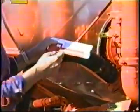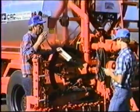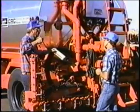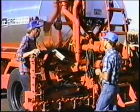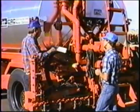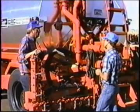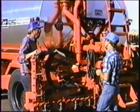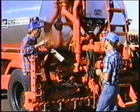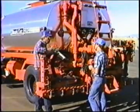Okay, so that means on this truck, all we have to do is hold the engine up to 1200 engine RPM. While we're doing that, dial the pump in to read the 135 gallons per minute that we had for this particular spread rate. Okay, because we know that this truck will travel 400 feet per minute at 1200 engine RPM in the second gear. So we don't have to go out and make a dry run. We can do that while we're parked. Once we've made that setup, then we put it in gear, take off spreading.